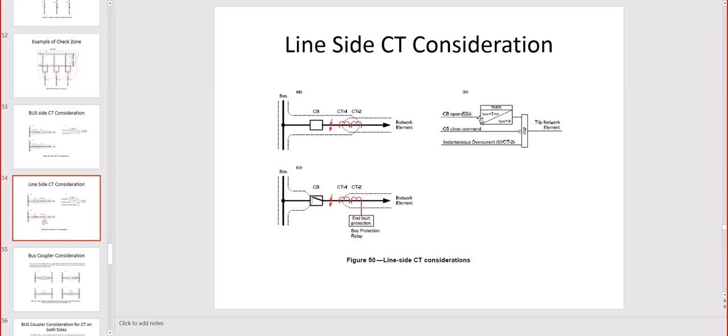Now there is a time delay here, and the time delay to open or to close is because the breaker needs a time to open or close. So we will not trip instantaneously on this breaker fault which reads the current across from one side to the other side of the breaker. Later we will have a time delay. Now on the closing, that time delay is very short, is a quarter of a cycle, because we have by standard, IEEE standard for breakers. By the way, these slides are from IEEE C37.234.